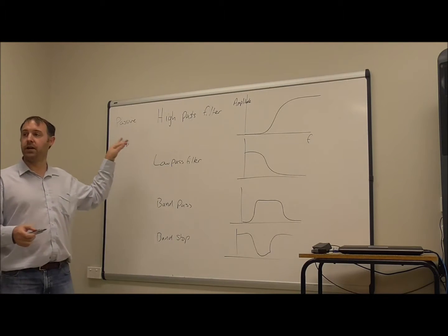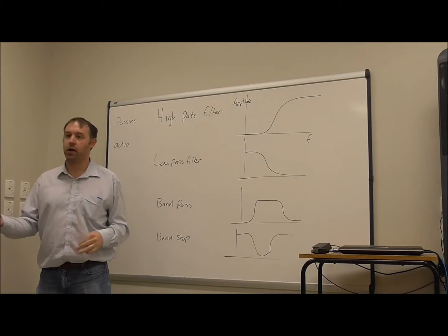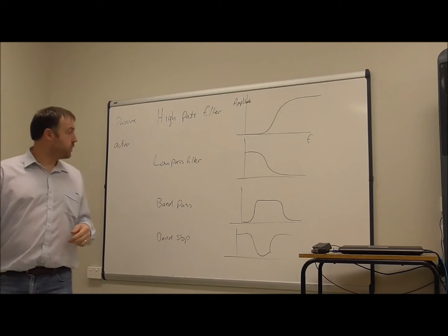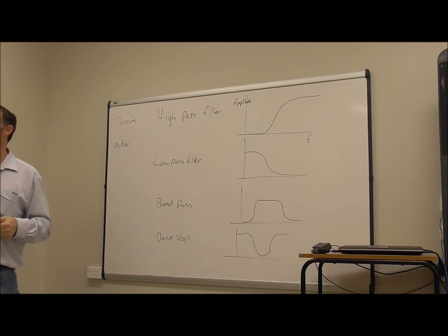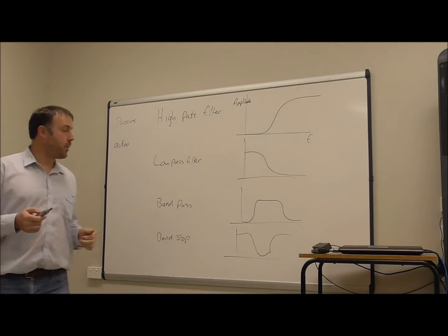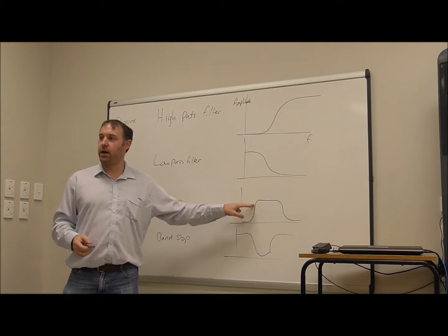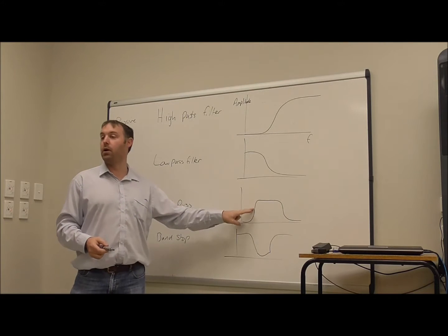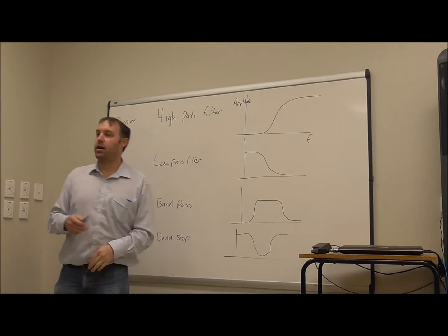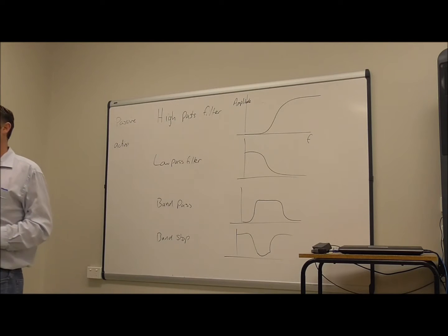And I can also, if I'm making a filter that is like a band pass or a band stop, make these independent of each other. We'll talk about how they interplay when we have multiple filters with each other and the problems that occur with that later. But basically, if I want to make a circuit where I can control just the lower cutoff frequency or just the high cutoff frequency, I can do that with an active filter. It's quite difficult to do with a passive filter.